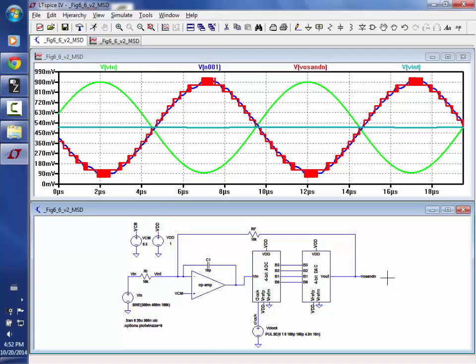No, I've never seen that. That's why I put it in. The only one I've ever seen is 1 bit. But I don't want to give you problems where I know the answers, right? I want you to think, and then if I try this, I do this. The big benefit of the passive is you don't have the op amp. So you basically could have zero static power dissipation if you were using switch capacitor. You could come up with something that works really clever, something worth publishing.